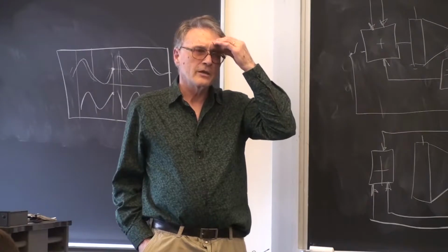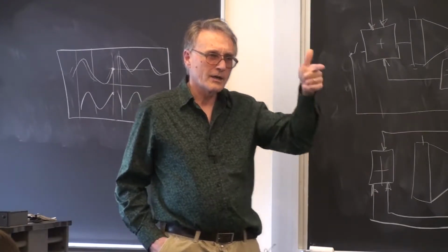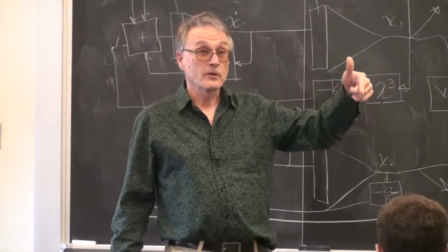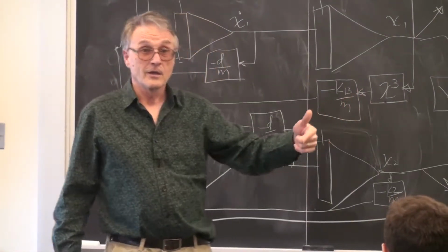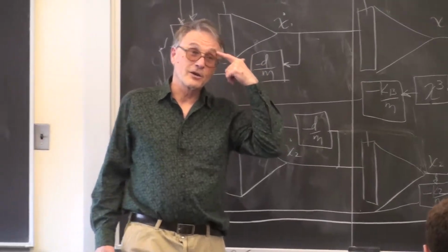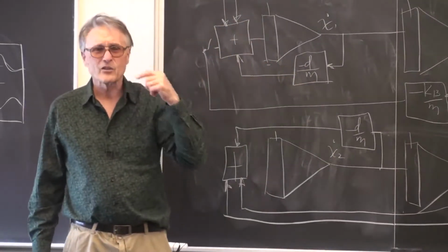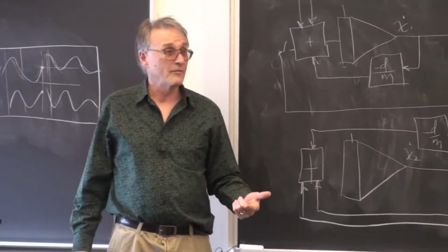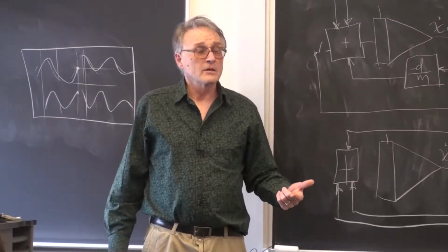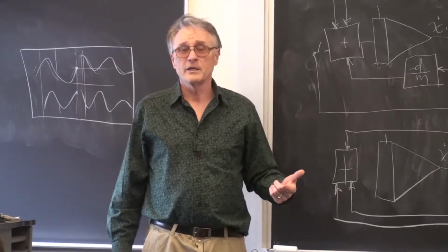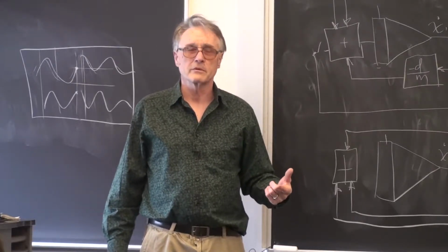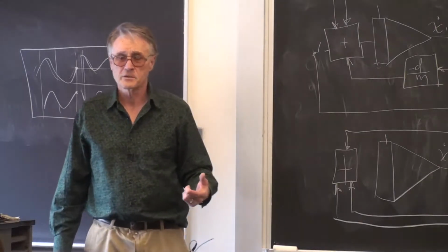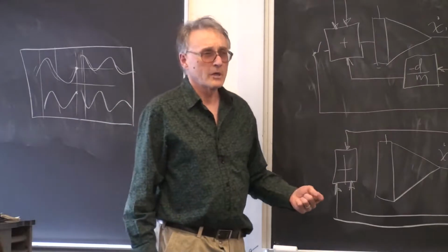I would say that even though the Nyquist criterion says you only need 2 points per cycle to understand a sine wave, the psychological criterion is that you need about 20 points per cycle to understand a waveform. You say, all right, well, we got 640, 20 points, 640 divided by 20. Sounds like about 32 cycles across the screen. That's the maximum you want to have.